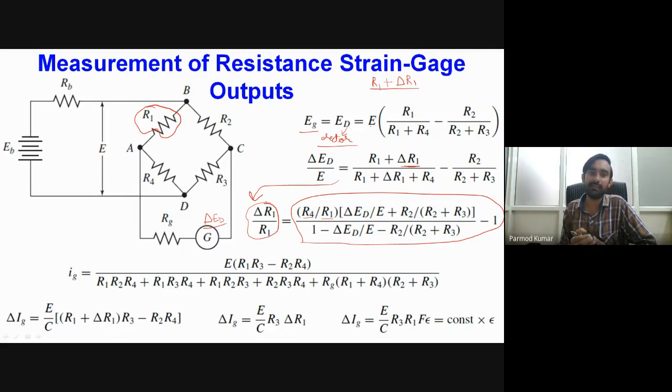Okay, and that particular value of the strain is having linear dependence on the pressure, so obviously we can relate directly over here the pressure and particularly the voltage signal whatever we are getting. Okay, so this is one of the ways where we are actually dynamically measuring the voltage across the galvanometer, and this voltage is actually related to the value of the pressure.